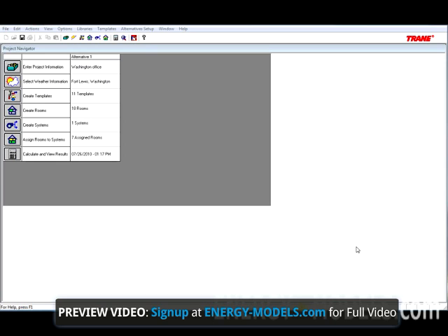To some people, the purpose of load calculations is readily obvious, but to the typical energy modeler, it may not be so apparent. Let's take a moment to determine what we are calculating. The building load is the worst case hour of the year. We need to determine it in order to select the proper air conditioning unit.